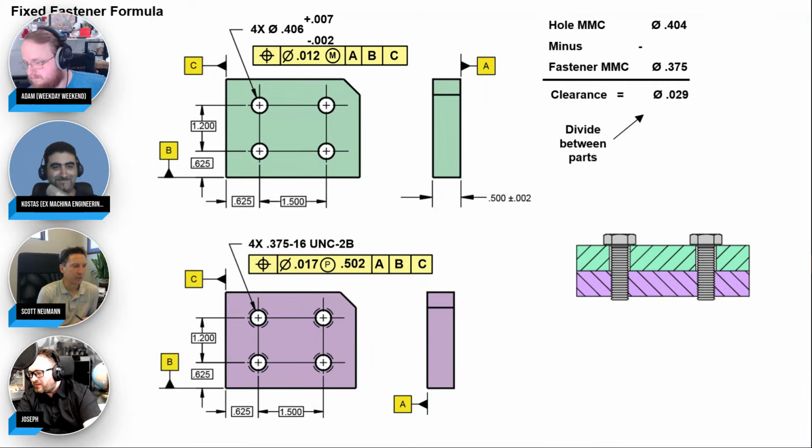Yeah, this happened to companies who would design parts way back in the 80s and 90s, and it was kind of hard to measure off the pitch. So they would reduce the tolerances to accommodate the current inspection methods. But all of a sudden, this drawing still works today, but we're still stuck on those old quality methods when we've got these amazing tools that can measure right down to the nth degree and measure it properly. So yeah, don't hide the measurement deficiencies by compromising your product definition. Got it.